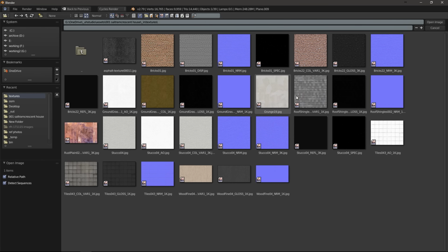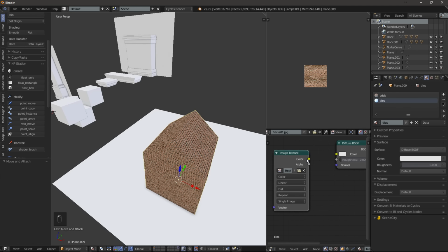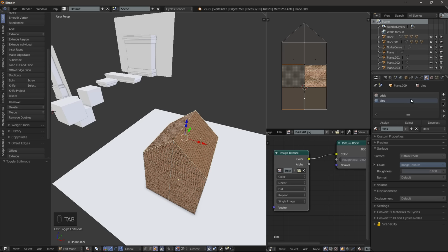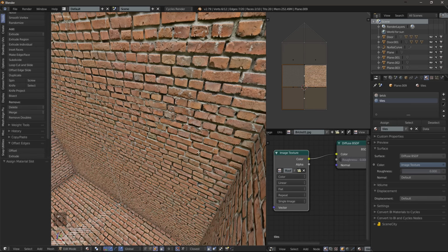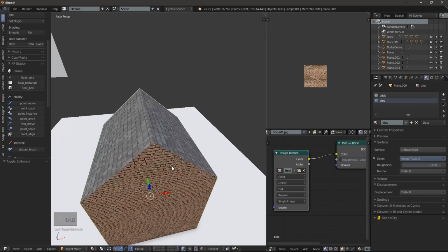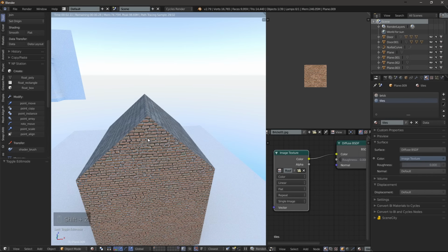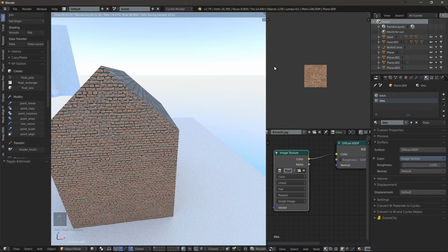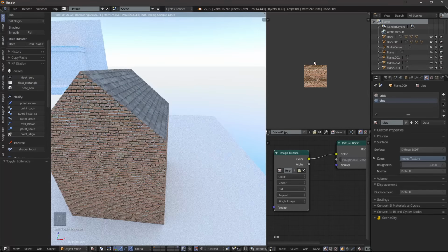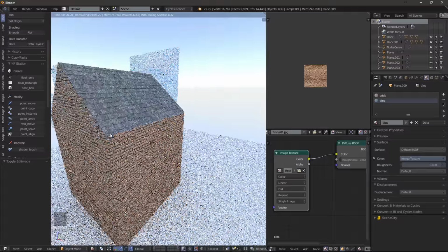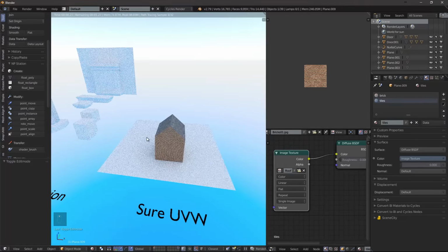So I'll add some tiles or roof shingles for the color, and in edit mode I'll just assign that. So you see it keeps the UV coordinates. So that's without any need or with minimal need to go into the UV editor. Again, very useful for architectural modeling.